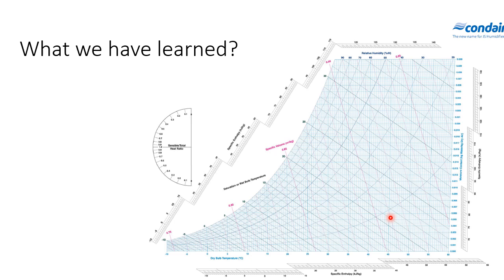And so let's see how we can present room temperature, or room condition, in the psychrometric chart. Let's say we have a room air measured by a sling thermometer. We have 22C dry bulb and 16C wet bulb.